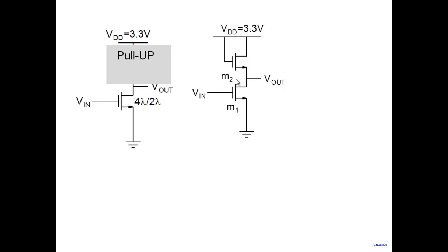So somebody could suggest this. What about this? Will this work? Somebody says, take a transistor and short gate and source. If you short gate and source, what will happen? M2 would be always cut off because gate to source voltage is less than threshold voltage. This is permanently off. Obviously, it will not work, right? But sometimes good ideas emerge. You have to go through a bad idea, right? You have to go through this. Okay, it doesn't work. But under what condition can you make it work?